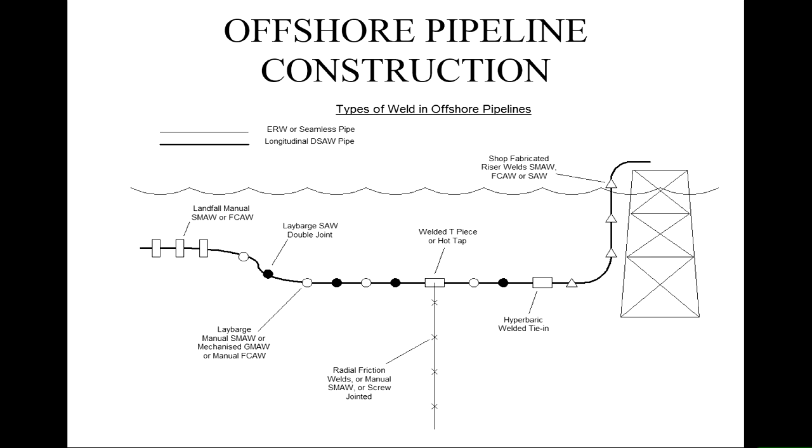With the hyperbaric welding, would you get more diffusion of hydrogen and other gases into the liquid weld? Certainly increasing the pressure, you might expect increasing the solubility of hydrogen. Actually, the pressure effect on solubility is relatively small. People say that hydrogen processes are worse, but actually solubility isn't too different. So what the problem normally is that under a hyperbaric welding condition, there's nowhere for the hydrogen to escape to. So the ambient hydrogen levels go up, and that has a bigger effect rather than the pressure that you're dealing with. Potentially explosive environment. Absolutely, yeah.